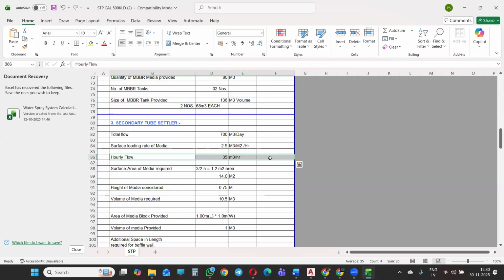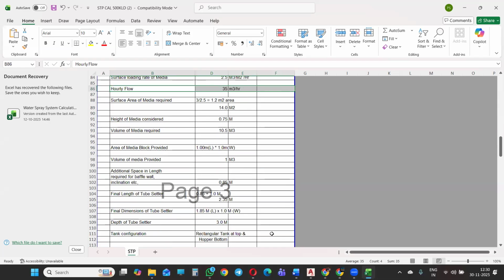राइट। एक्सेल शीट्स में फॉर्मूला लगा हुआ है, आपको ये नहीं पता चलेगा कि कौन सा टैंक कितने घंटे काम कर रहा है। खाली एक्सेल शीट में वैल्यू डाल दी तो आंसर आ जाएगा। बट प्रैक्टिकली हमें डिजाइन पता होना चाहिए कि कौन सा टैंक कितने घंटे काम कर रहा है, इसका यूज क्या है, और हम बाईपास लाइन कहाँ से ले सकते हैं, मैनहोल कहाँ से बना सकते हैं, और मैनहोल का साइज कैसे कर सकते हैं। दैट्स क्लियर।